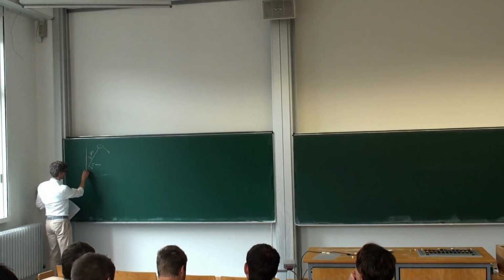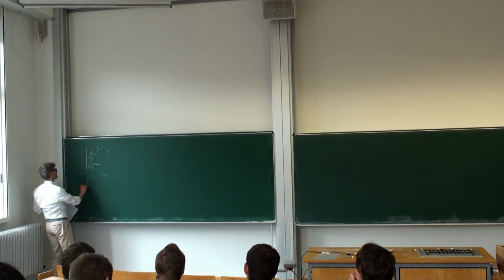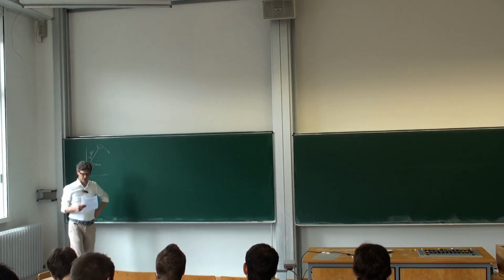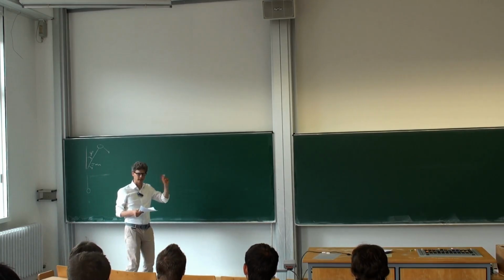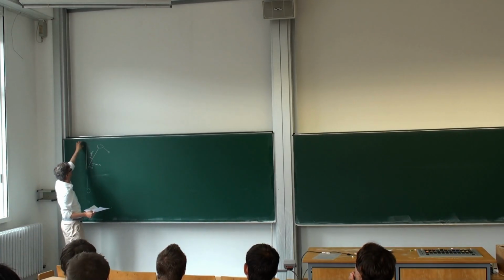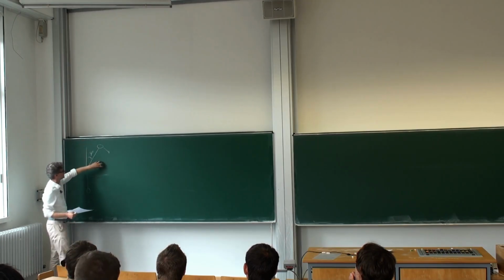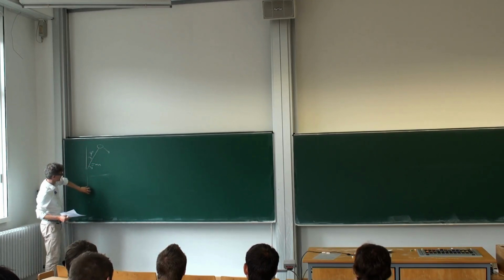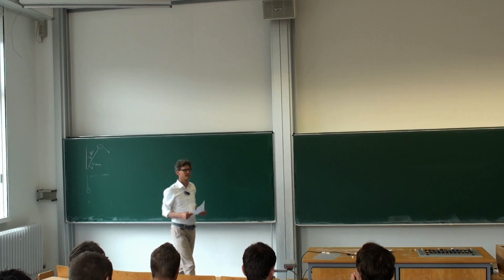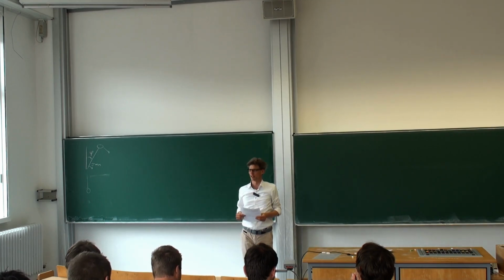And we want to start with a hanging position and we want to move it up with minimal effort of torque. Actually the objective is a mix of state penalties, so penalties on the deviation of the pendulum from the top, and the square of the u's, but if you start here, you need to have some controls in order to make it swing up and move to the top. So that's the problem we want to solve.